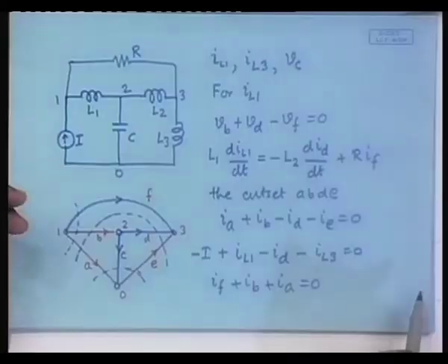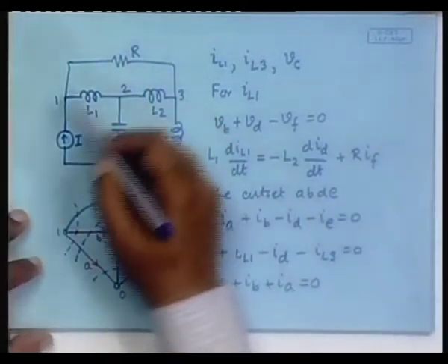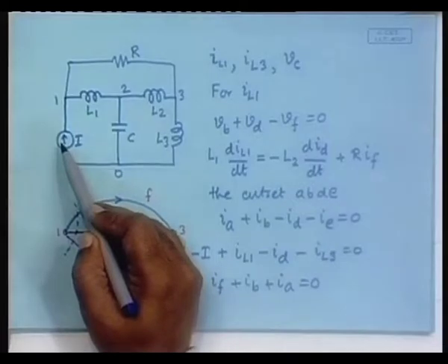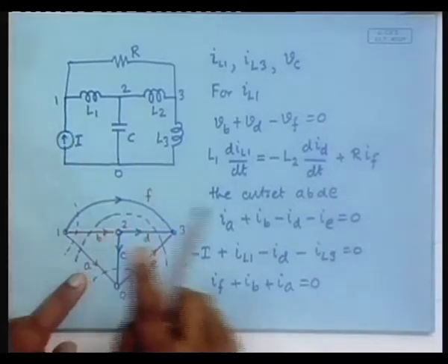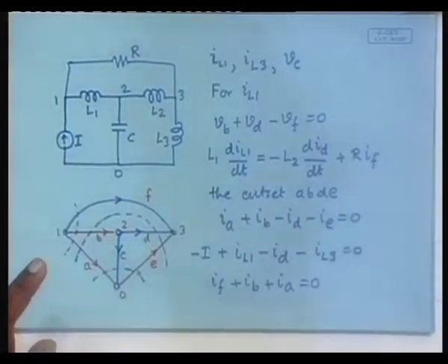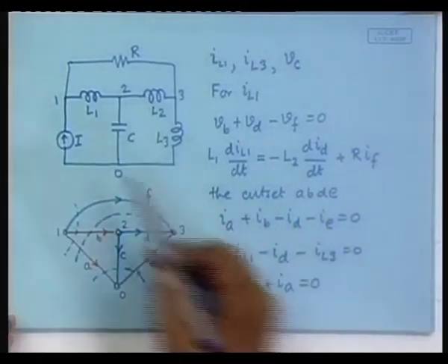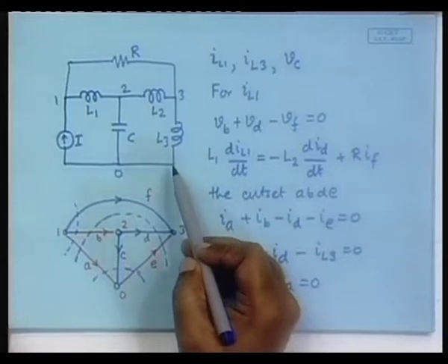And in fact, when you actually connect the circuit in this way, this will cause a problem, because this cannot instantaneously vary. If it does, then di/dt will be applied as a voltage on these inductors.